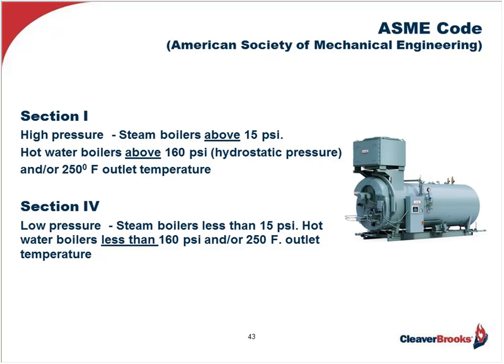Now, I mentioned a bit ago that ASME code is quite specific about how these boilers will be constructed. And as such, it will detail things like boiler plate thicknesses to be used, the type of welding to be applied, when stress relieving is necessary, including the temperature and time, when and what to X-ray, hydrostatic testing, and so on. So it's really quite specific, also requiring, as previously mentioned, an independent inspector be in the plant at all times to witness specific boiler construction operations to assure the plant's quality procedures are not only properly followed, but they're applied.